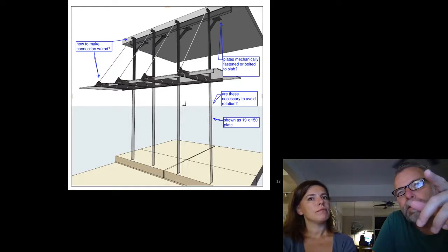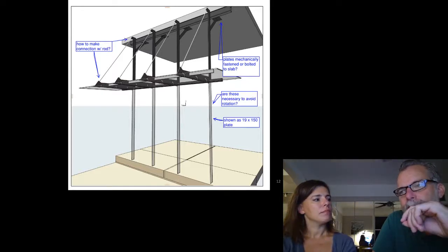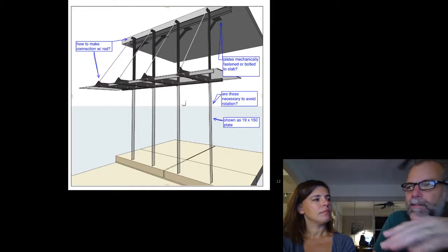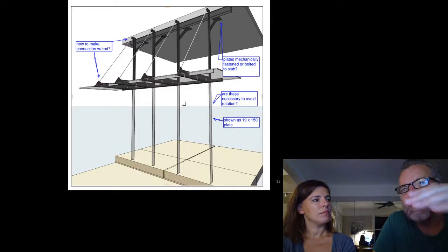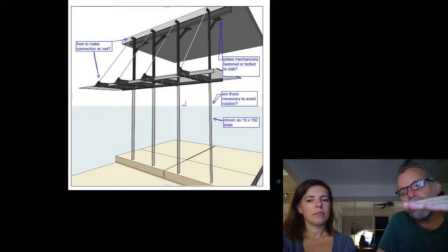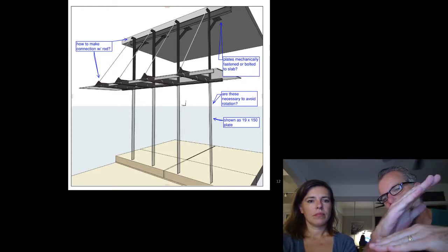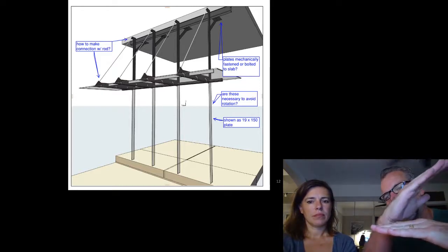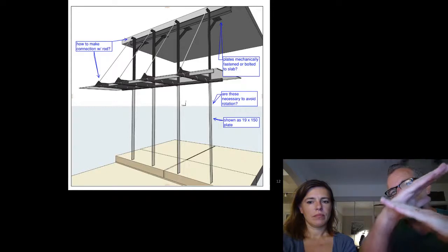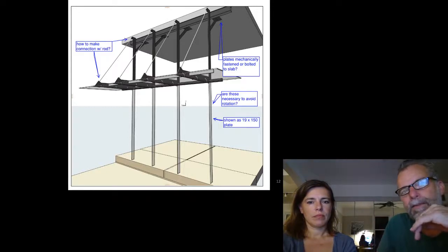So what we do is we pre-stress those rods so that they stay taut in serviceability conditions. At limit state, we're not so concerned, but at least at the serviceability condition, the loads that it's likely to see and that are likely to disturb people, we make sure that it stays in tension. And we can do that because the canopy itself is moment connected to the building. So when we tension that rod, we're not just lifting against the weight of the canopy, we're lifting against the moment connection.